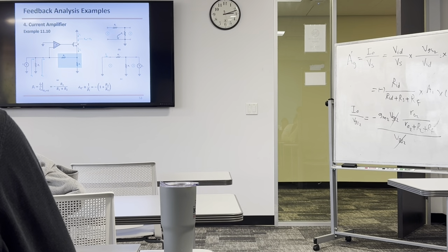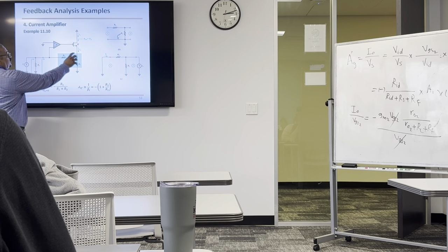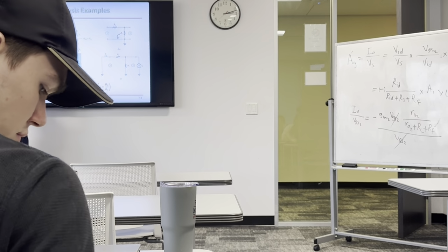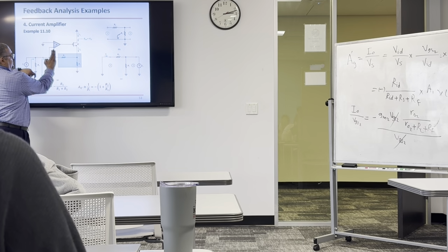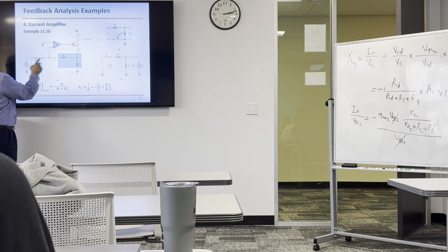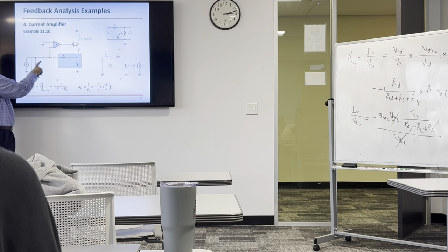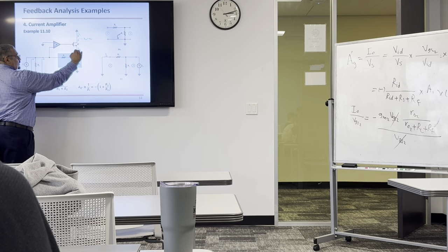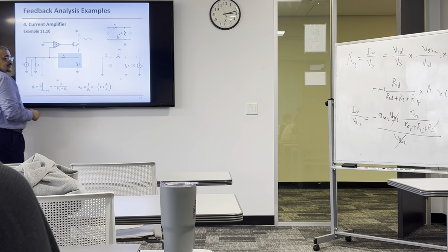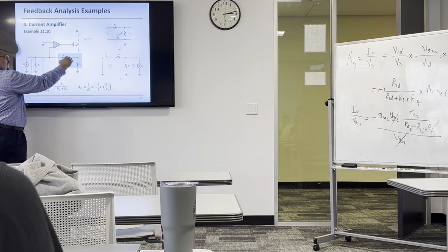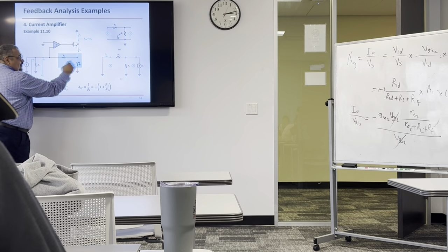I leave it as an exercise. If you have any questions, just let me know. It's the same thing, so you have to take these two. This is a current, this is a voltage. So when you cut here, are you going to short it? What do you think if you cut here and attach it here? This is current, right? Current is mixed in shunt, so you have to short. If you cut here, this is current, and current is sensed in series, so leave this off. Okay, so you're going to have R1 and R2 in series here and in parallel here.